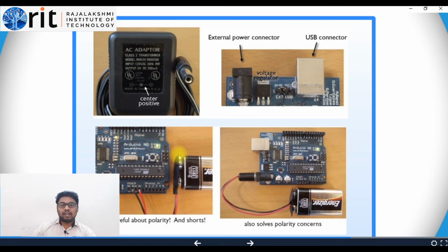Suppose your Arduino board is not standalone, for example you are creating a robotic car, then the device will be moving around, so you cannot use a wired connection to power up your Arduino. In that case you can use a battery, as the third diagram indicates.